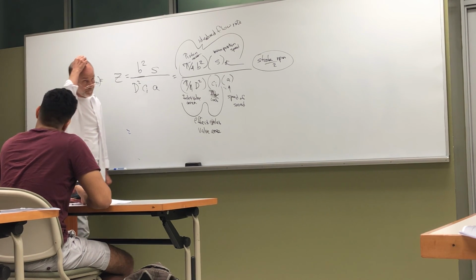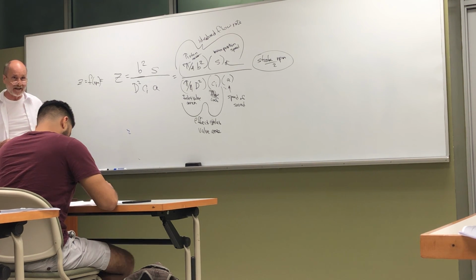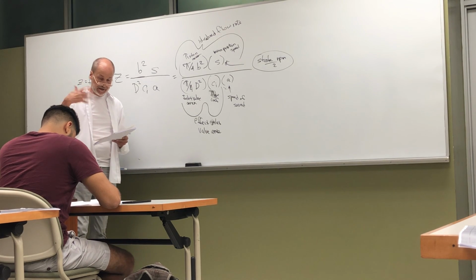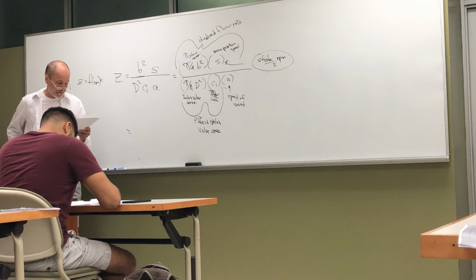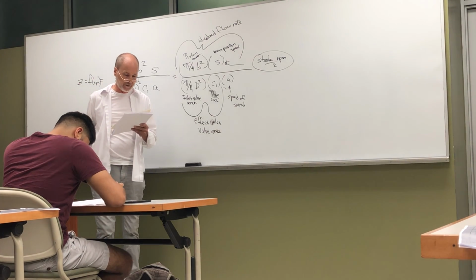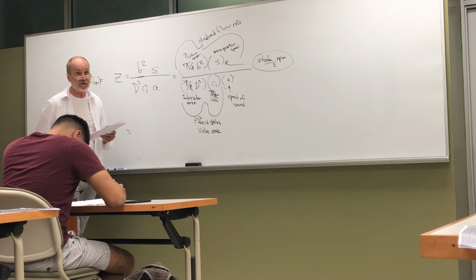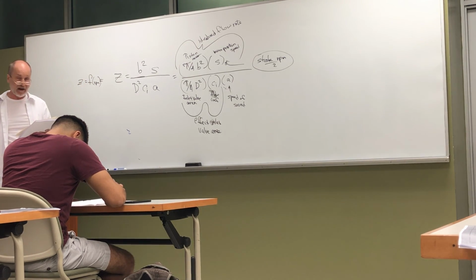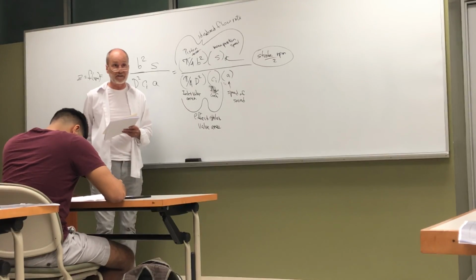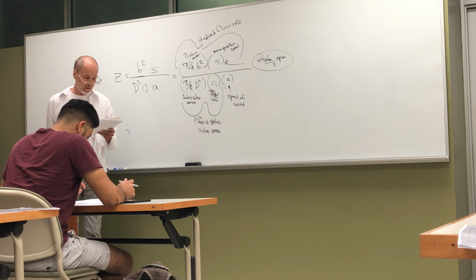Now what was found, and you can see it in the plot in the lower left-hand side and the upper right-hand side. In the lower left-hand side, we have a given engine. Data is taken repetitively. And we can see that at Mach index about 0.5, the volumetric efficiency begins to drop. The vertical axis there is volumetric efficiency. The horizontal axis is Mach index number, which for a given engine is only a function of RPM. Which figure is it? The figure in the lower left-hand corner.